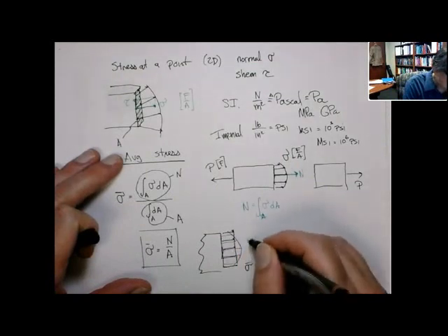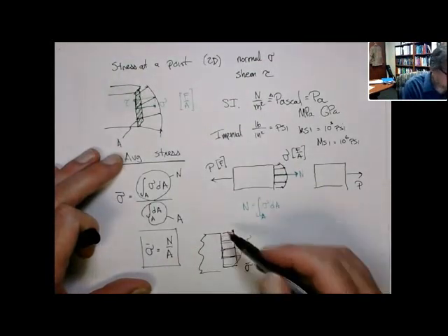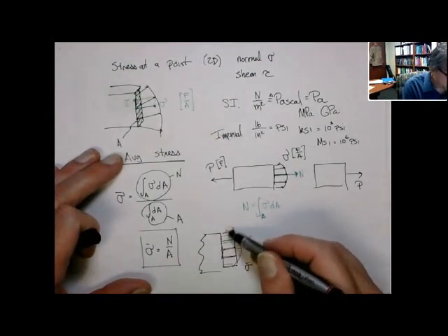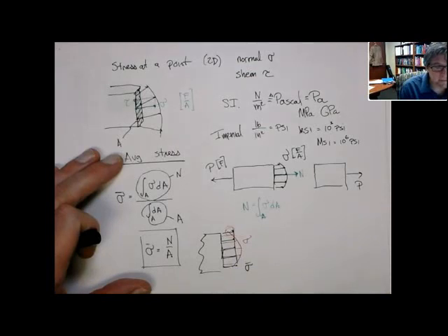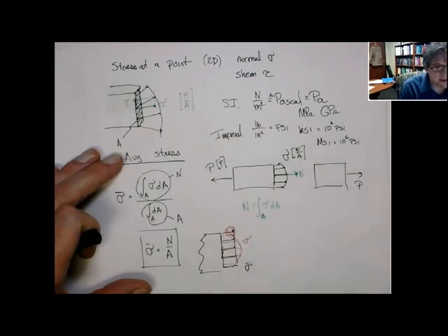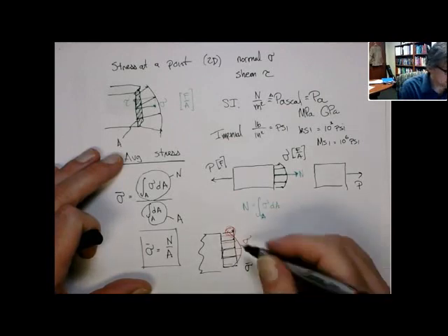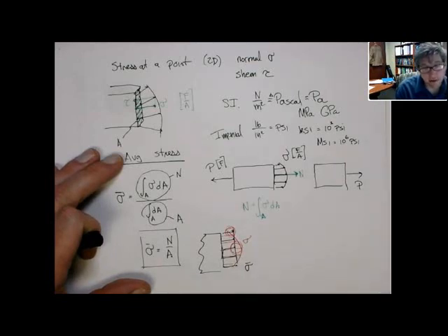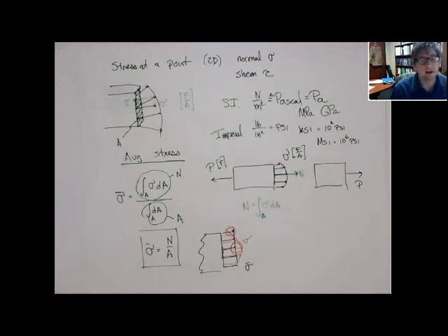Call this the actual stress. At some points, right here, the average normal stress is going to be higher than the actual stress. In some locations, it's going to be the other way. The actual stress might be higher than the average normal stress. That's the notion of average: some points are higher, some points are lower. So there's a bit of an error that possibly happens here.